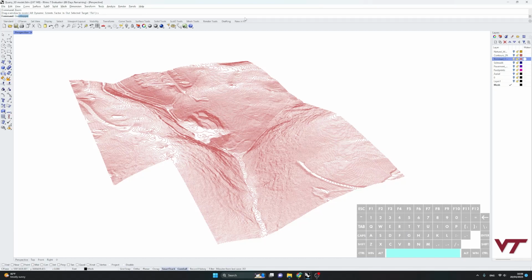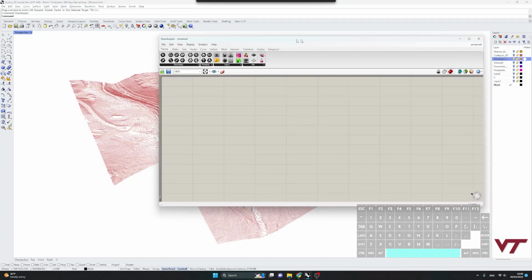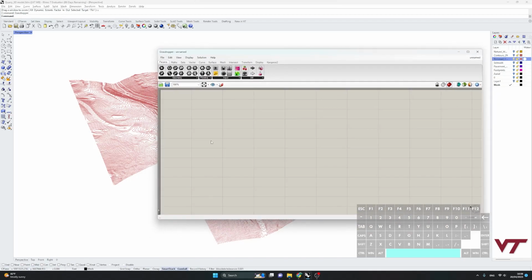But Grasshopper is really fantastic. It's a nice parametric modelling interface, which is used by a lot of architects, landscape architects, and probably interior architects as well. I'm also assuming industrial designers probably play with it because they spend a lot of time in Rhino. To start off with, we want to bring in a curve command. What these little commands or modules do is that some of them will tie geometry in that Rhino modeling space and bring it into this Grasshopper parametric canvas, and other ones will manipulate that within the canvas. It doesn't manipulate out there and here.